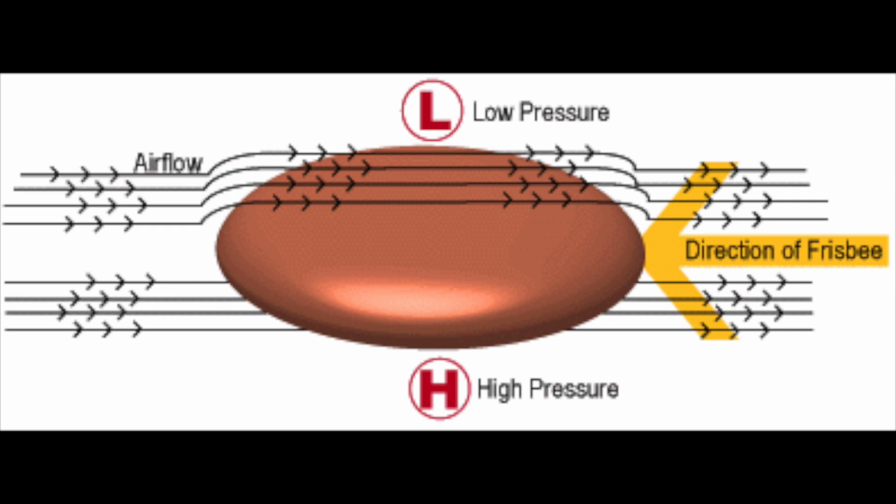As the angle of attack increases, the drag will increase, as will the lift generated. At larger angles of attack, the deflection of the air above the disc increases. This deflection of air creates low-pressure pockets, which correspond to a force perpendicular to the flow of air in that region.